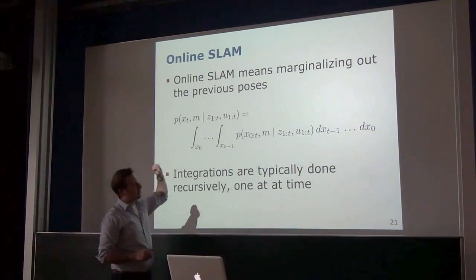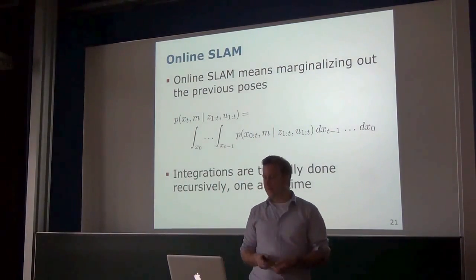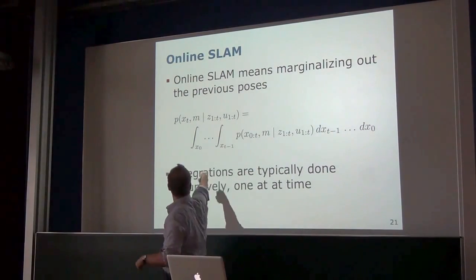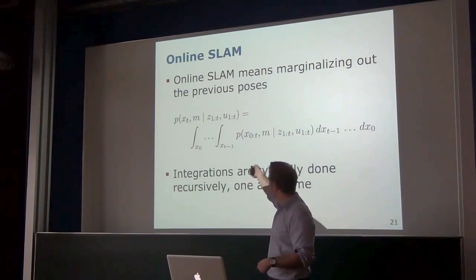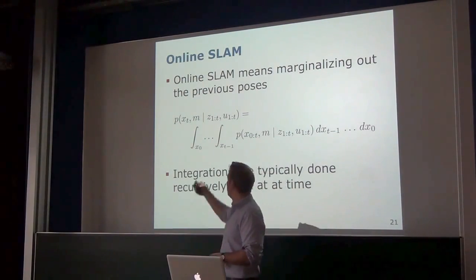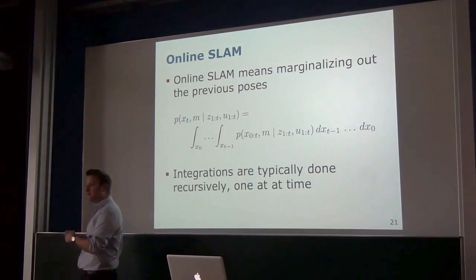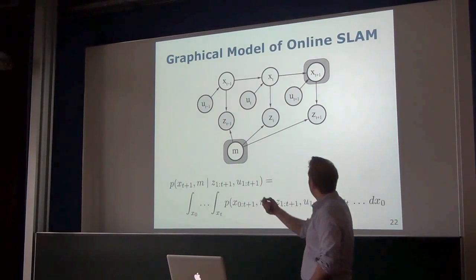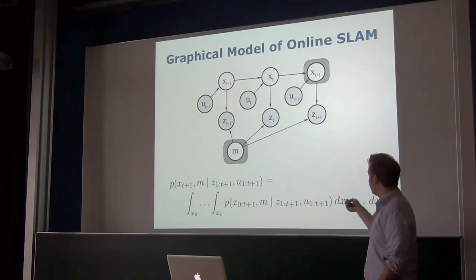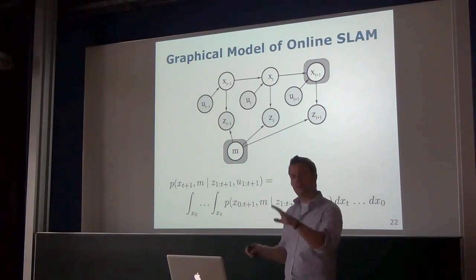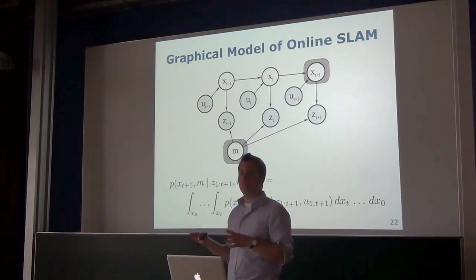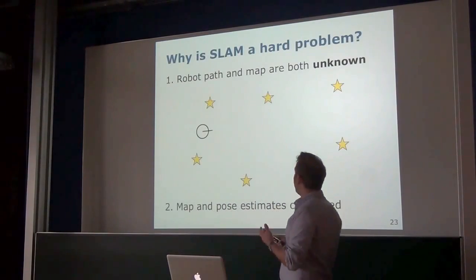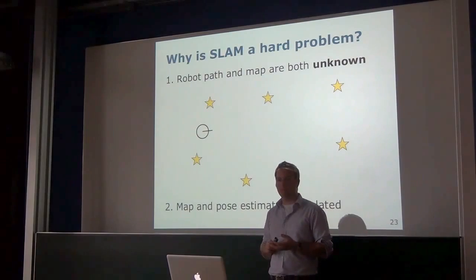This is actually an approach that most of the systems which try to do online SLAM take. At every point in time they do a computation and solve one of those integrals. They marginalize out the poses and only estimate the current pose of the system within the map of the environment. Just to give you the context. And then, as I said, express this exactly as marginalizing out all of the previous poses. But when we get to more details about the filter, you will understand that problem.